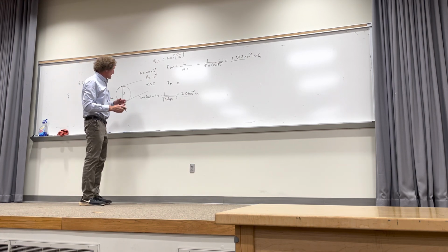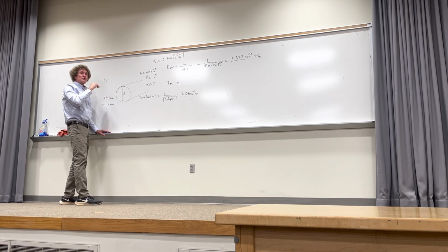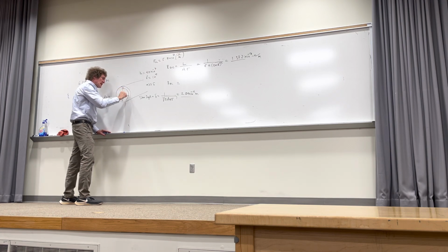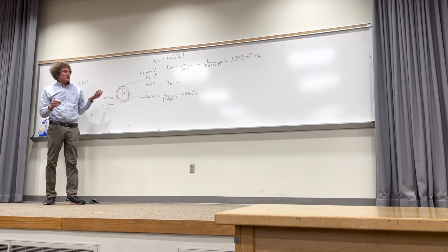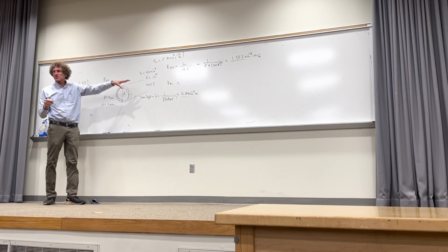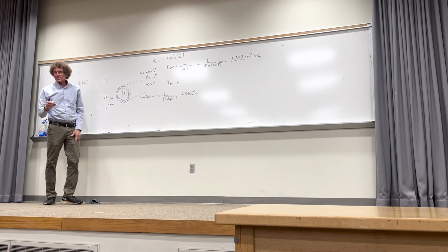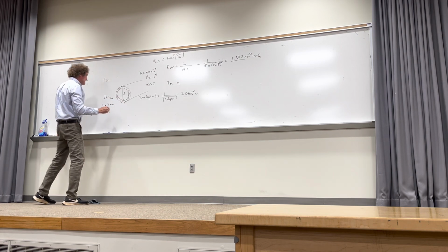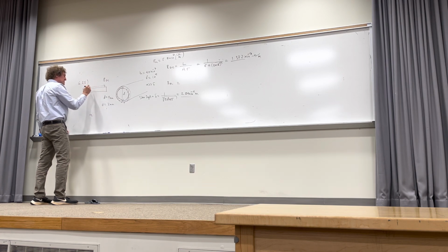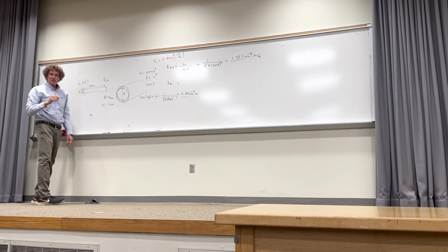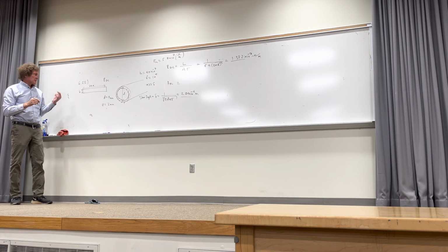Now, because of that, all the actual current that's flowing will be contained in 1 skin depth of the surface. I did this last time, right? Y'all remember this, everyone? So the only thing we have to change from the DC formula is the area. Length is per length, so nothing there. Sigma is sigma. And do you remember how I said to do this? If you just cut this thing and rolled it out, the length here would be the circumference, 2 pi times A, and the thickness here would be a skin depth, and that would be the area. So it's a skin depth times 2 pi A.